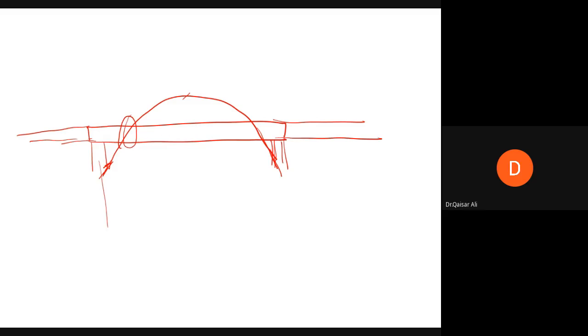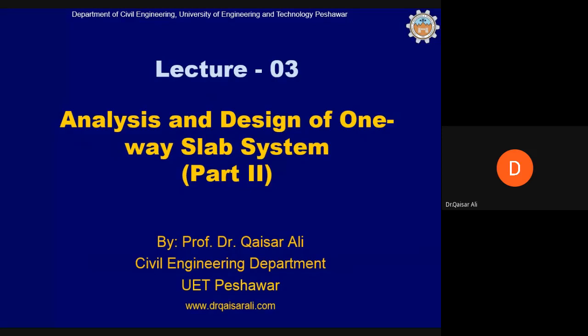So if there are 4 bars here, you can curtail or reduce some of these bars near the supports. You can make 4 bars into 2 bars. You can cut 2 bars so that you bring some economy to the project. And then because there is negative bending moment, 4 bars will be required here instead of 2 bars in this location. Okay, Ahmad? Yes, sir. Now it's clear, because of the moment. Okay, thank you, sir. Anything else? No, sir. Go further.